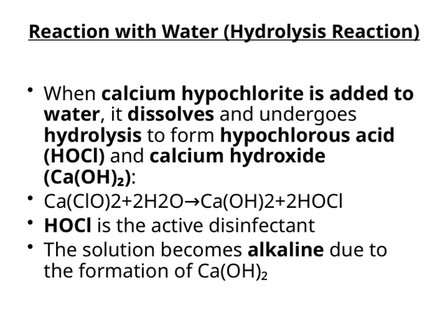At the same time, because calcium hydroxide forms, the solution becomes more alkaline or basic. This shift towards a higher pH is a direct result of the calcium hydroxide. Understanding this hydrolysis reaction helps us see why calcium hypochlorite is so effective as a disinfectant, because it releases HOCl when dissolved, which is potent against microbes, while the solution's alkalinity influences its stability and reactivity. This reaction is a fundamental step in how calcium hypochlorite functions in water treatment processes.